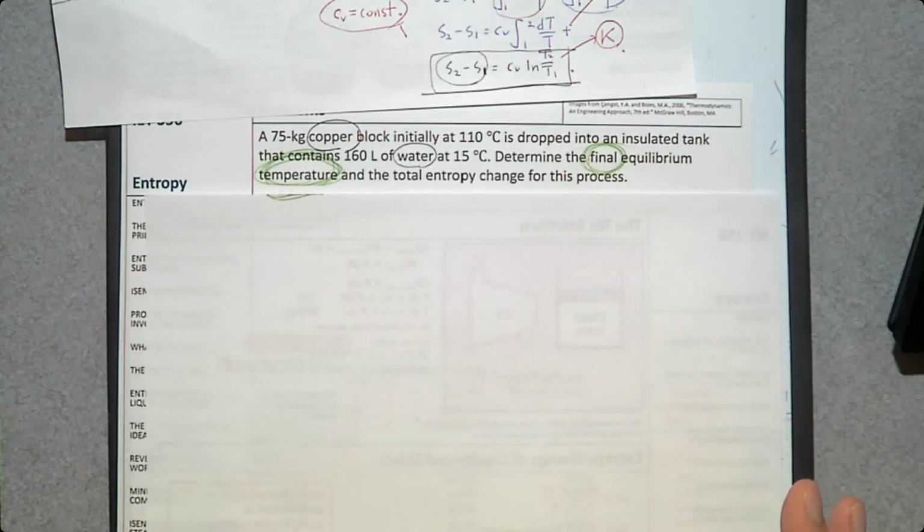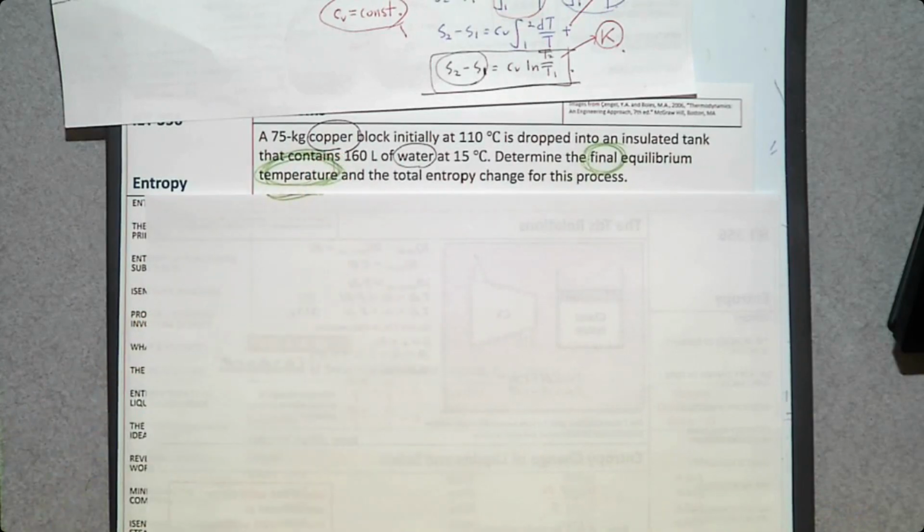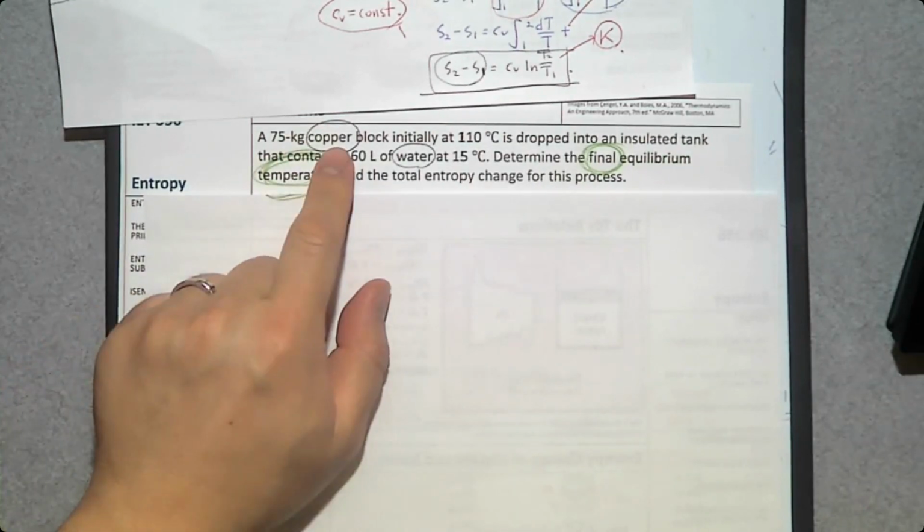There are two energy balance equations, one for a closed system, the other one for an open system. So you need to determine whether it is a closed system or an open system first. We have a copper block. How do we know whether it is a closed system or an open system? The question is going to be, whether the mass of the system changes or not. If the mass is constant, it's a closed system. If mass is changing, it's an open system. What about this copper block?